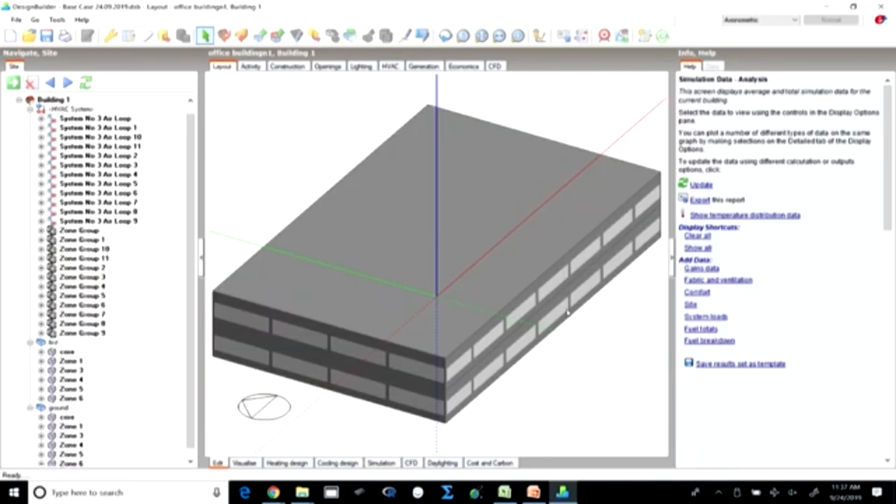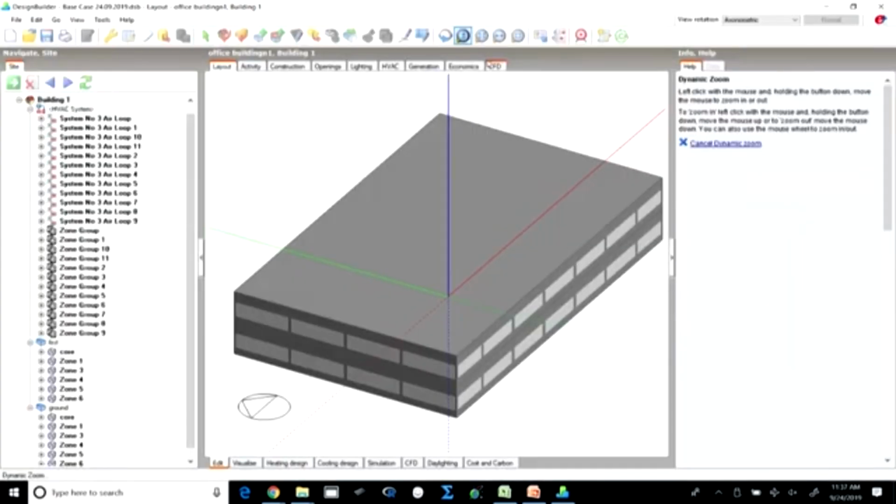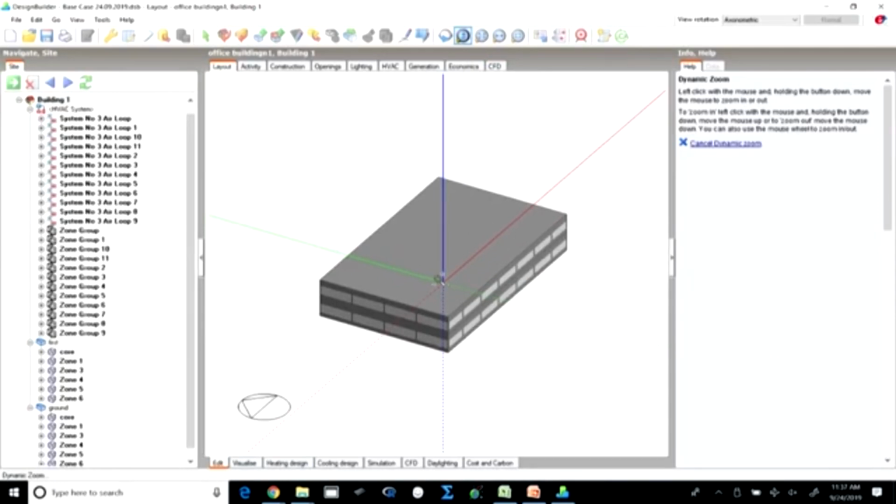Now, if we have to calculate the average performance of the base case, then we rotate the building and create 4 different cases, as I have mentioned earlier, by rotating the building 90 degrees. We simulate each of these 4 cases, oriented in 4 different directions, for annual simulation, 365 days, on an hourly basis, 8760 hours specifically. So each building will be modeled for the entire duration of a year, and an average calculated to determine the performance of the base case.